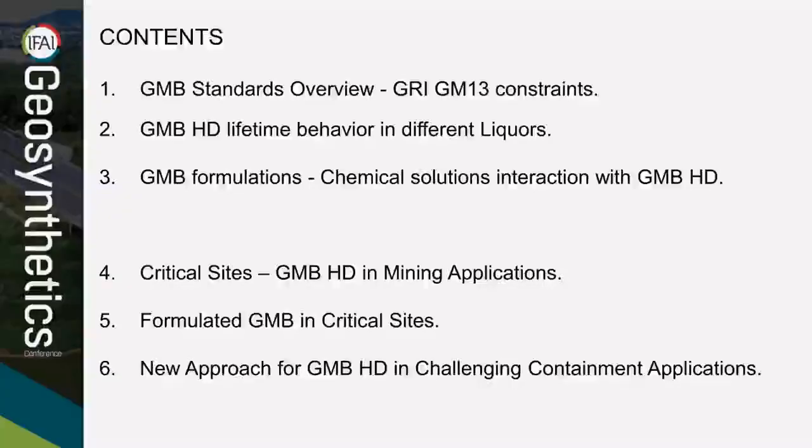Our research is divided in two main sections. The first part is split in 3 points, where we have done an overview of HDPE standards, an internal research by testing some traditional geomembranes to understand their behavior in different liquids. And after that, we have assessed how chemical solutions interact with and impact these regular HDPE geomembranes.